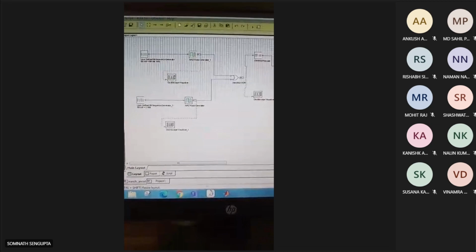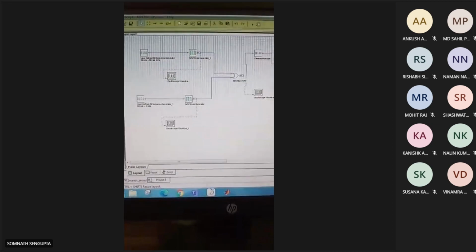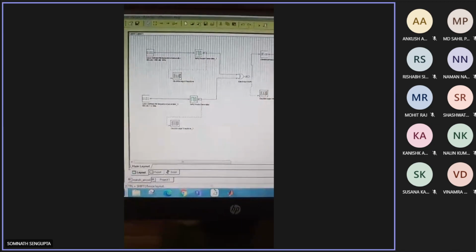You know that in hardware you have seen Manchester coding. Generally at the mid-bit position there is a bit transition according to the input data. If it is 1, it goes from high to low. If it is 0, it goes from low to high. So those things are implemented and transmitted through optical fiber.